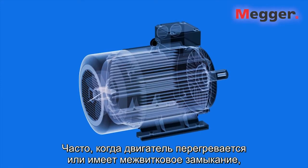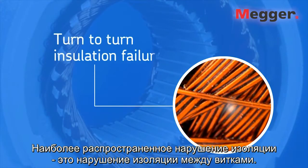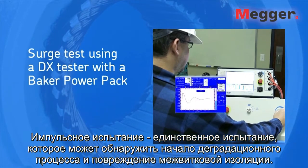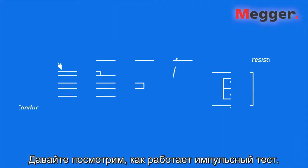Oftentimes, when a motor overheats or has a turn-to-turn failure, the excessive heat will cause a ground wall insulation failure also. The most common insulation fault is a turn-to-turn insulation failure. A surge test is the only test that can find turn-to-turn insulation weakness and failures. Let's look at how a surge test works.